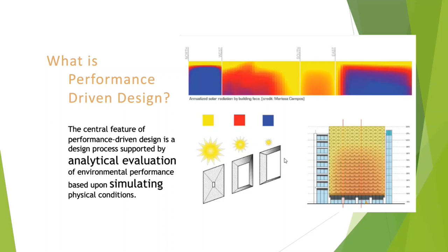This depends more on your design. You could choose really large transparent openings if this is facing north, or if you want to block the sunlight from the west, then you choose smaller openings, right? Or it could be something parametrically controlled in Grasshopper. You can feed the heat map into the modeling process.